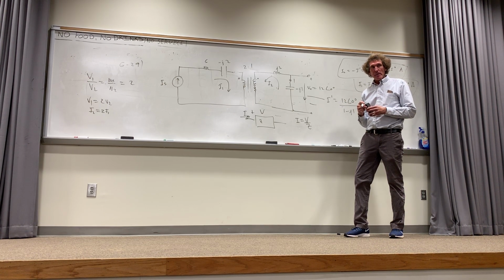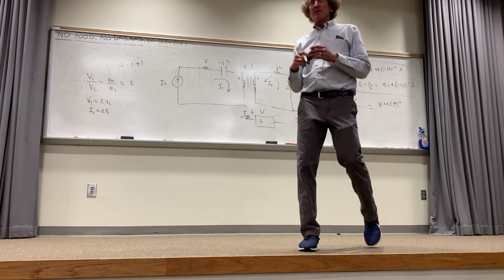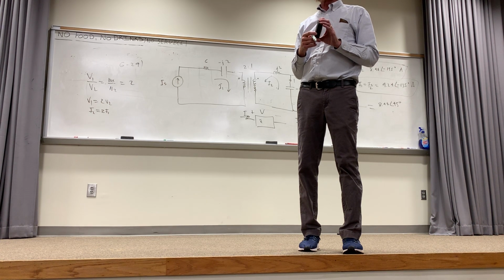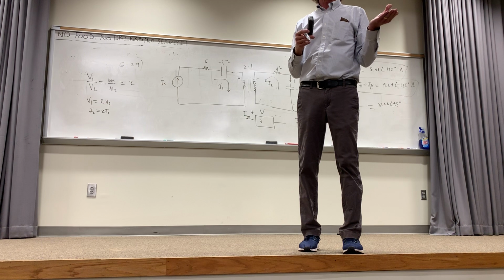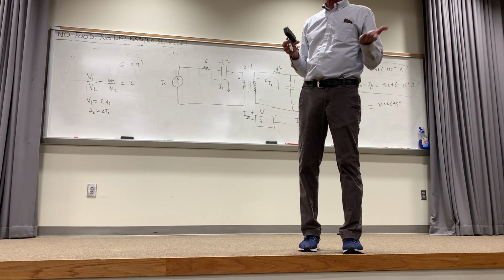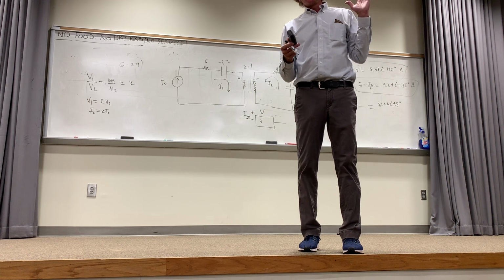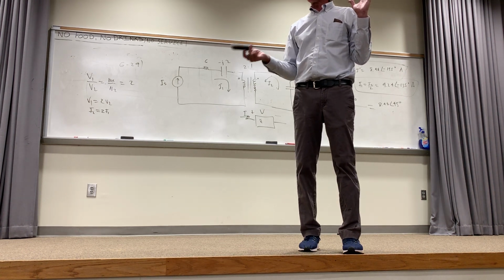What happened to change the angle from 45 to negative 135? Well, technically I wanted to put a minus sign in front of it, right? But what does adding a minus sign actually do? It just changes the phase by 180 degrees. So I added 180, or actually subtracted 180 from it. That's the thing you keep in mind always. Whenever you're talking about polar numbers, if you want to make the number negative, you just add or subtract 180 to the angle.